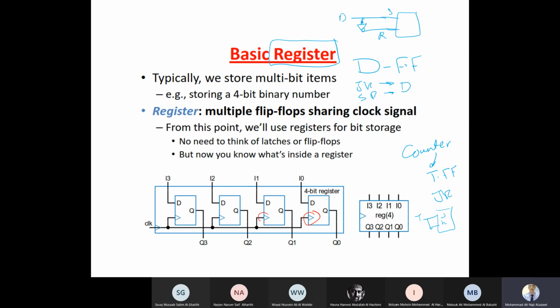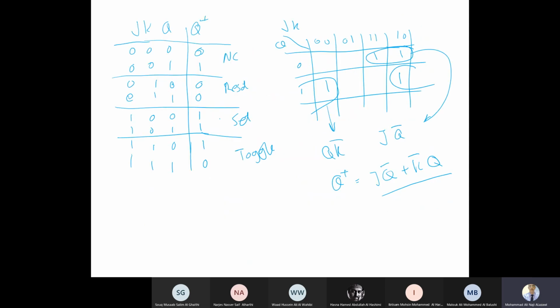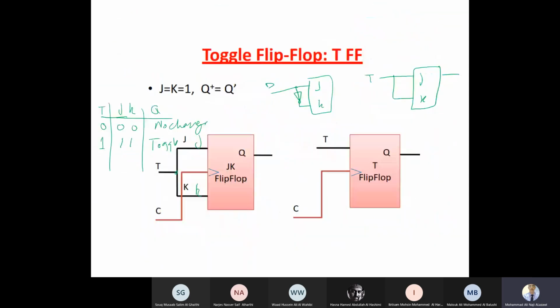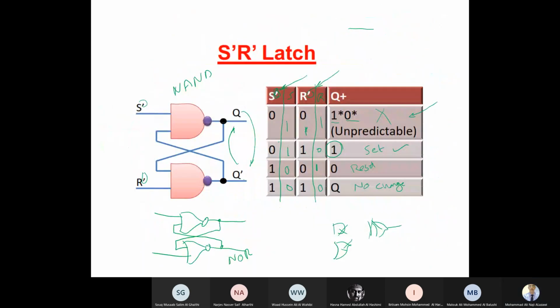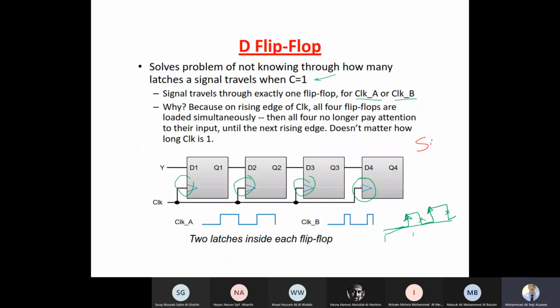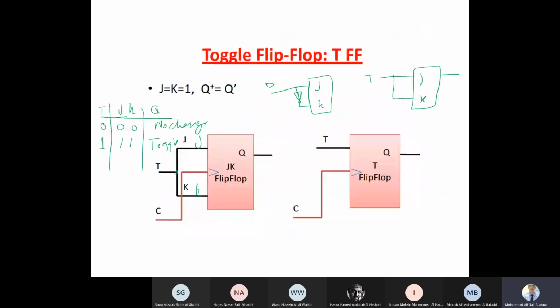That means they share the same clock signal, and we've taken an example and we saw how that happened. But what's the difference between this example and the previous one? Please focus with me. If I go back, yes, this one is called serial. Why serial? Because I have one input and one output. So if I want to enter the values to the flip-flop, I have to move the bits from one stage to another. That's why it's serial. The other one is parallel.